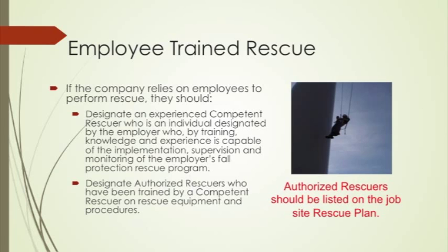If the company relies on employees to perform rescue, they should designate an experienced, competent rescuer, who is an individual designated by the employer who, by training, knowledge, and experience, is capable of the implementation, supervision, and monitoring of the employer's fall protection rescue program. The competent rescuer should designate authorized rescuers and provide the needed rescue equipment and procedures training.